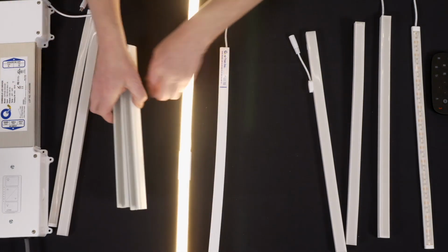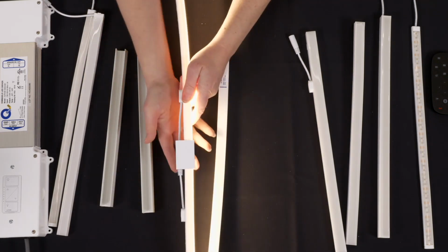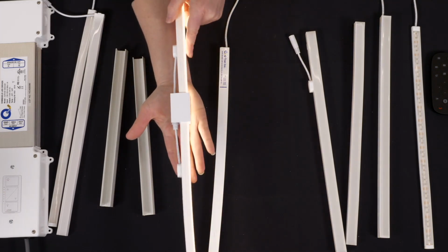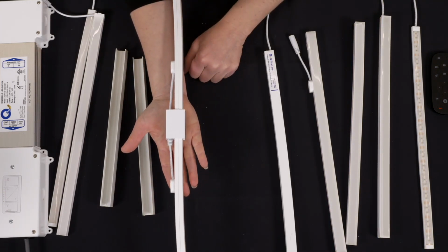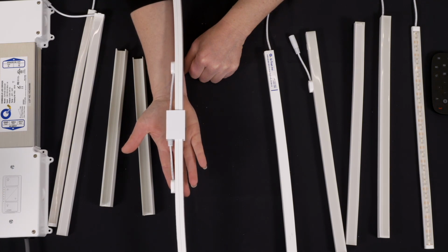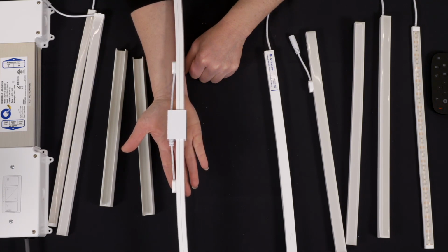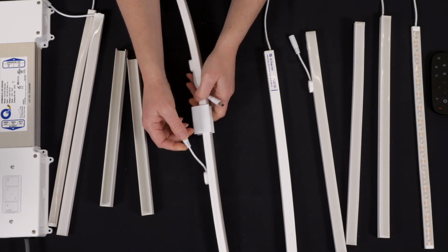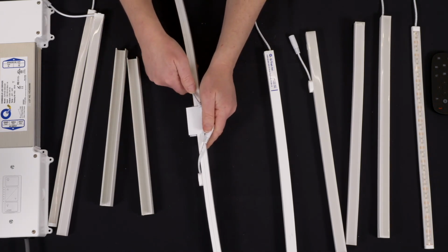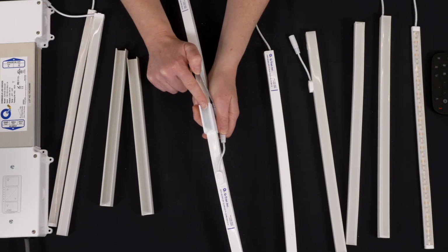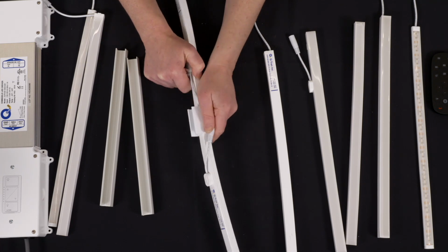The original H-shaped channel was initially designed for use when somebody was applying to stone. And no one really wants to put a screw into very expensive, especially imported stone. So typically in those applications, someone would likely epoxy a backer board and then take the lower legs and straddle that backer board and screw right into the backer board that is attached to the stone finish.